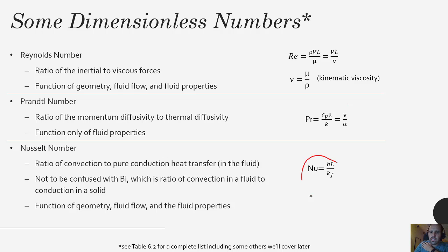So this is the definition of the Nusselt number, but if you recall, the correlations give us the Nusselt number, so then we have to back-solve from that. We run the correlation to get the Nusselt number, and then we apply the characteristic length and the thermal conductivity to get h. So you'd get something like h is equal to the Nusselt number times k over L.